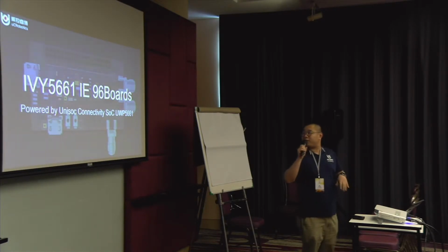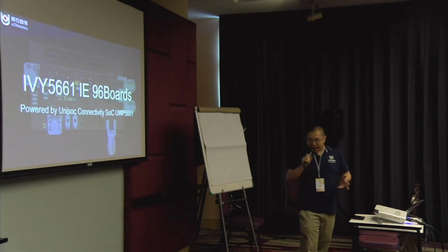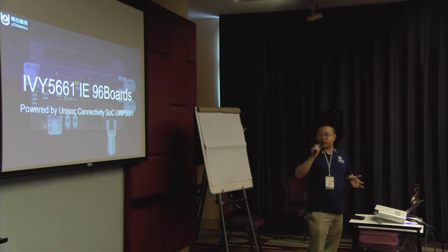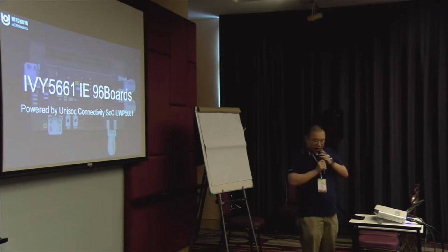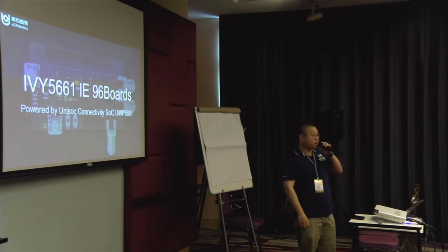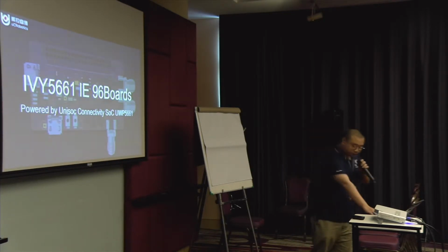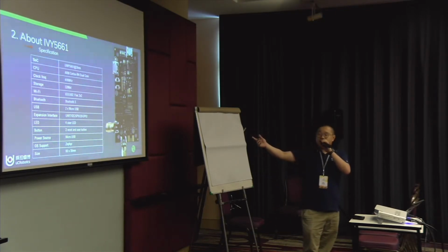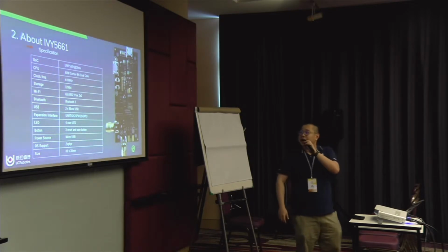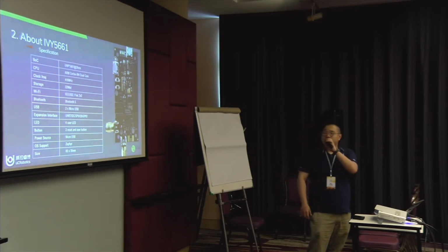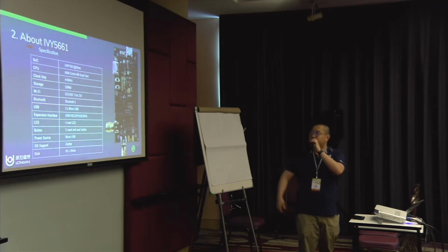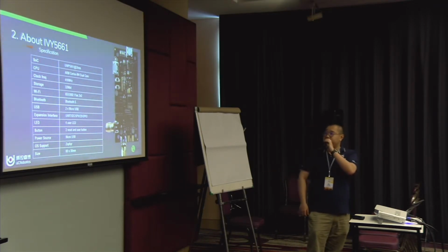So what is IVY5661? Actually, it's an IoT edition 96Board powered by the UniSoC connectivity SoC UWP5661. And it was announced at the last Connect in Vancouver. And here's the spec of 5661. It uses the UniSoC UWP5661 SoC, which contains an ARM Cortex-M4 CPU, and the clock frequency will be 416 megahertz.